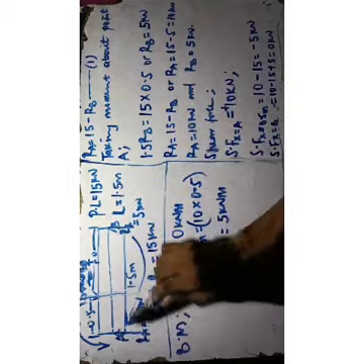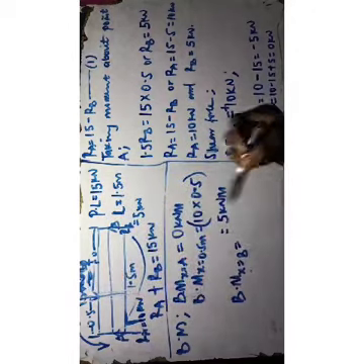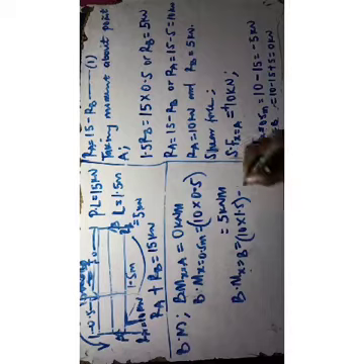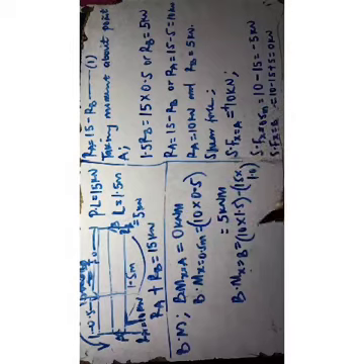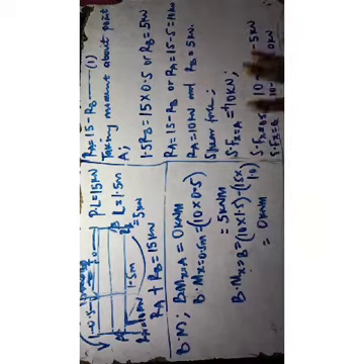0. You can also calculate by taking 10 times 1.5 minus 15 times 1.0. So that will be 10 times 1.5 minus 15 times 1.0. So you see finally 15 minus 15 will be equal to 0 kilonewton meter. So from this diagram and from this solution, you can now tabulate